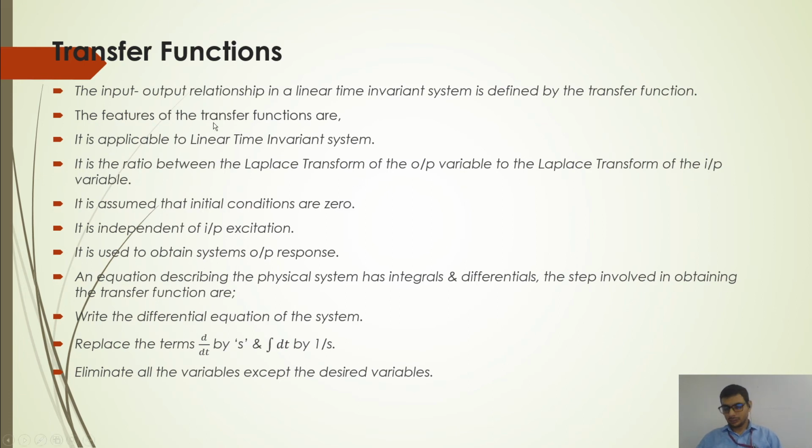The transfer function is defined as the output upon input in the Laplace domain. For example, let us consider a system having an input, a process, and then an output. The Laplace transform of output upon the Laplace transform of input is often referred to as the transfer function of the system. This can be done by taking the Laplace transform of the equations.